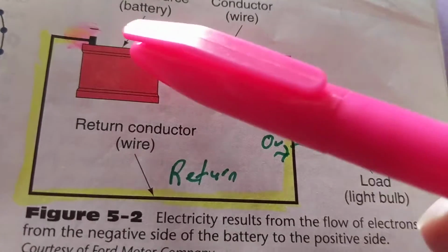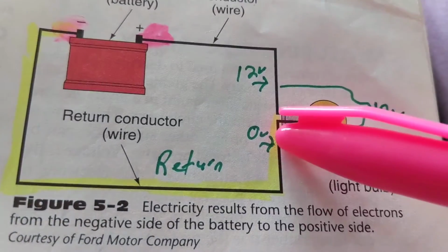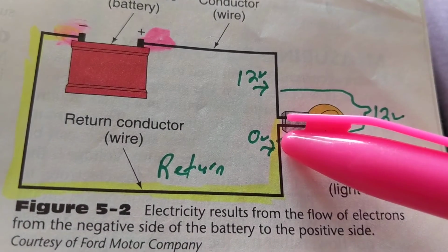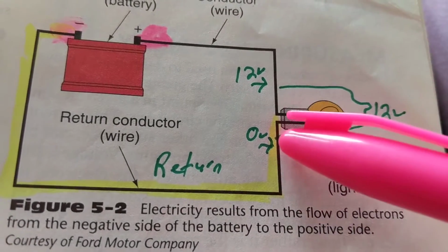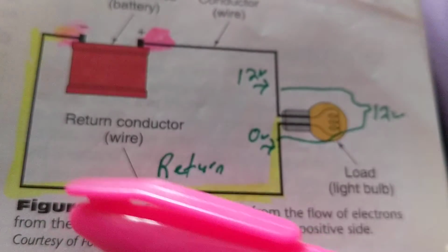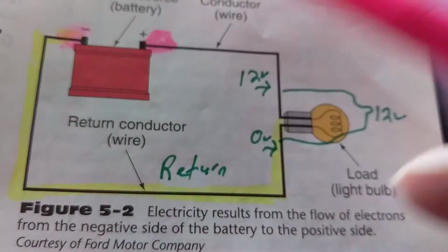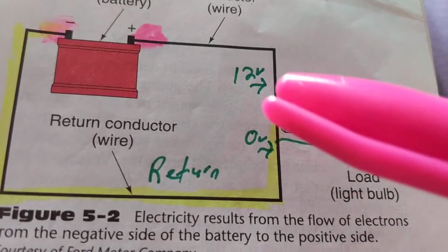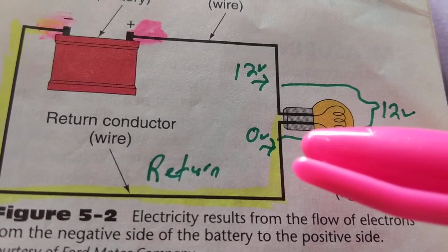If you look at this now, 3 volts over here will give you 3, instead of 0 volts back to the battery, now we have 3 volts over here. Okay? Now, you have 3 volts because of this high resistance path that was just introduced by all this white substance that corrodes. It looks like you've seen it, probably looks like cocaine and all that, right? You take hot water and then you clean it off, the post and the battery post and all that.